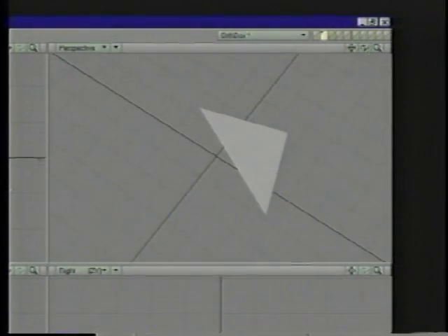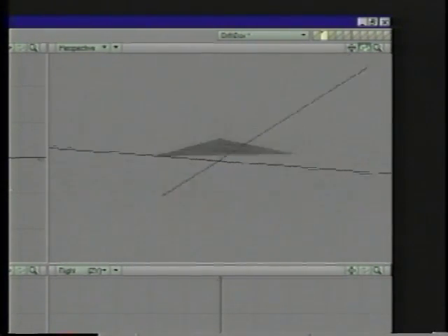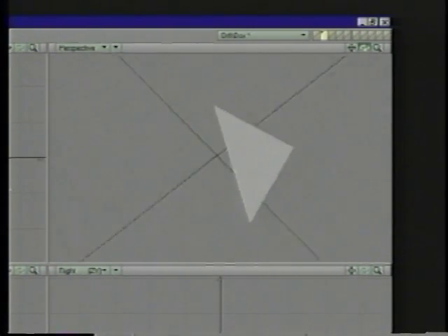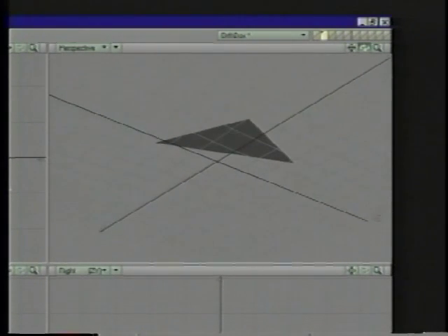And you'll look over here in the perspective view. If I rotate it, I'm seeing different sides of different polygons, and it's messed up. It's basically just messed up. And if you have polygons like this in your object, you're probably going to get all kinds of rendering errors in Lightwave. You're probably going to get flickering polygons or just black holes in your polygons.